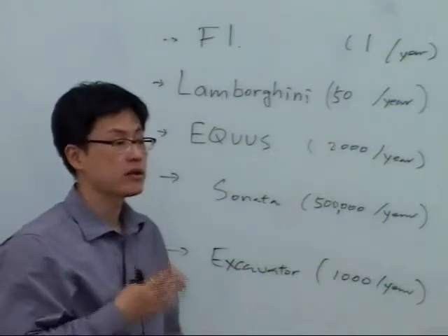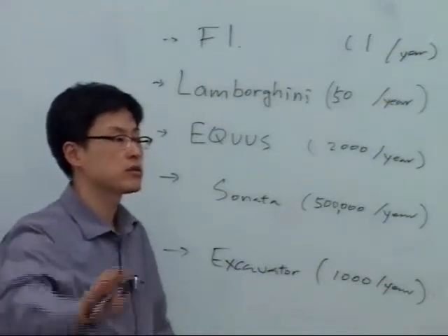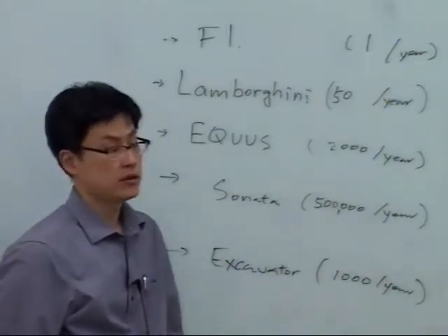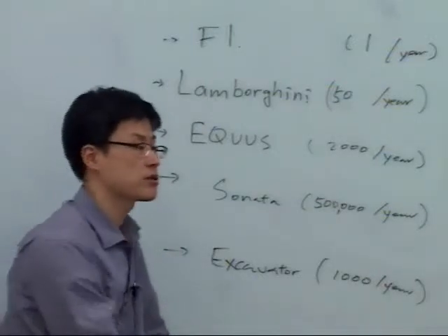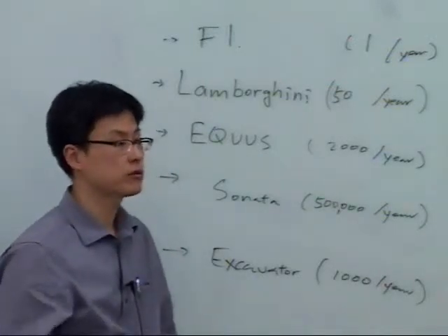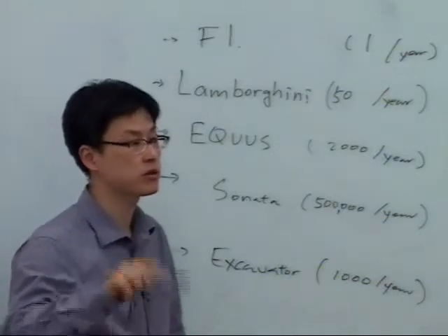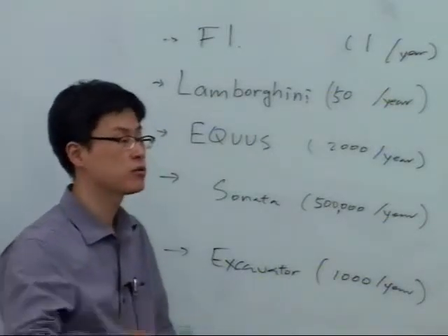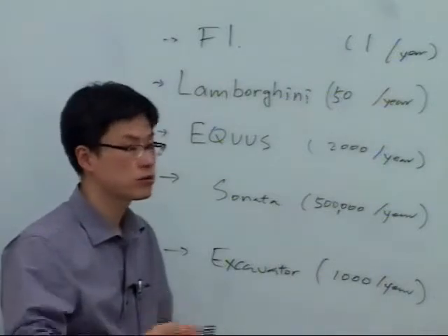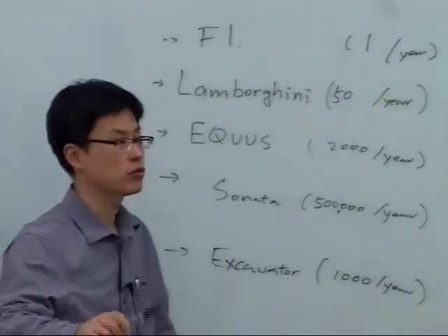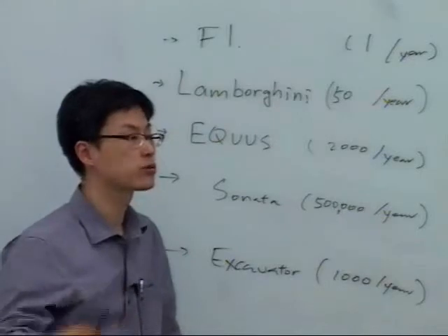Batch is to think of a lot in front of some workstation. The reason to use a large amount of inventory in front of that workstation is that the process in that workstation is really, really fast. So you don't want to starve that machine. You want to run that machine all the time.